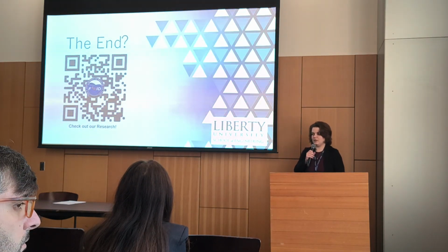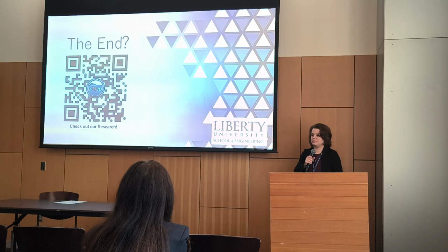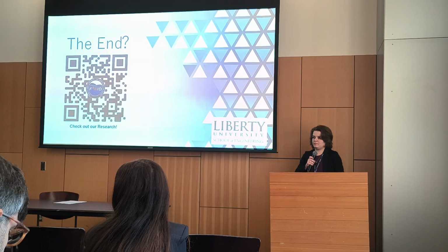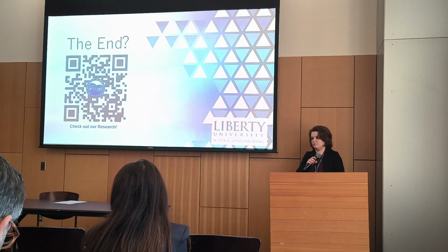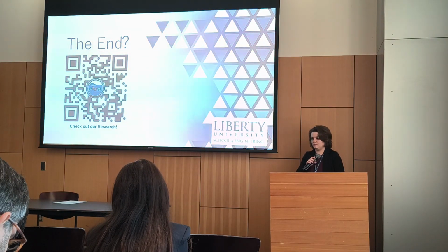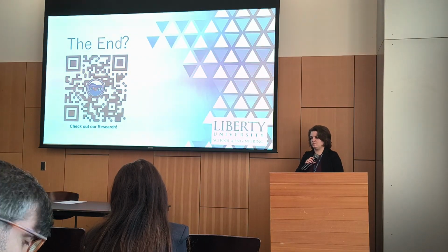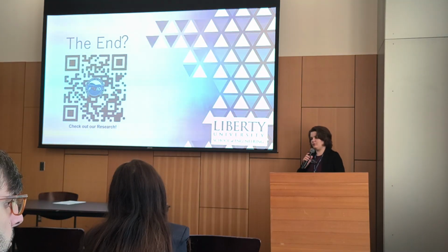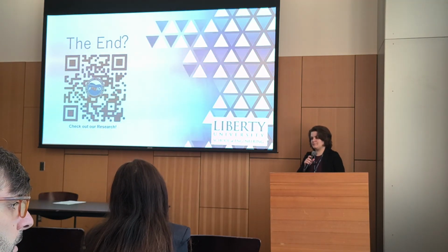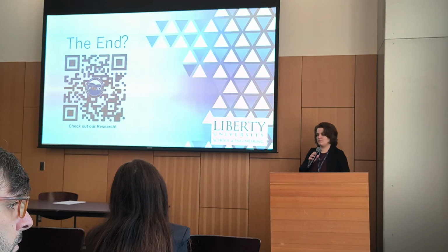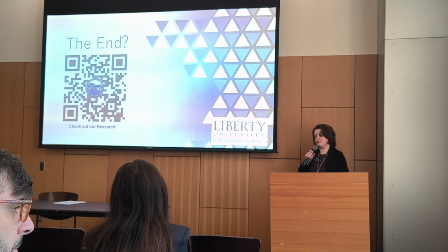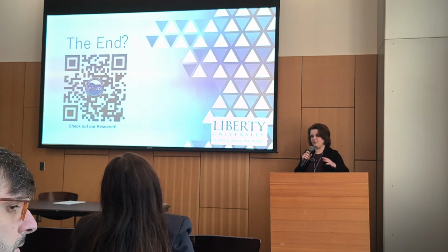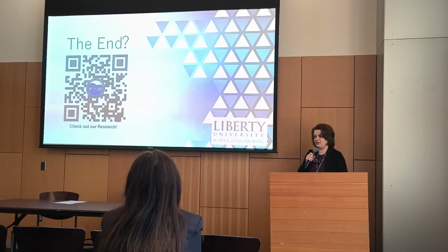Oh, everything. Okay. So when did you start averaging the LES? You reported velocities, for instance, of those kind of fluctuating moments. So when did you start averaging? I guess what were your initial conditions? Did you use the RANS to initialize the LES, or was it just a zero? We just used from zero. So it was like LES had its own separate modeling that it just had that 6.7 meters per second velocity.